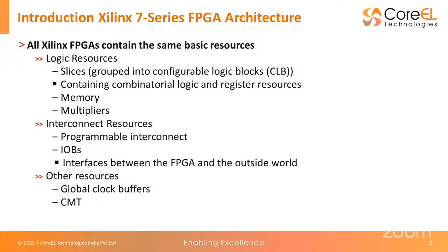When we talk about logic resources, we have something called slices. These slices contain multiple logic resources, whether it be your LUTs, your multiplexers, your carry chains, your flip-flops. All of these are available within your CLB, and this is the most important block when we're talking about any FPGAs.